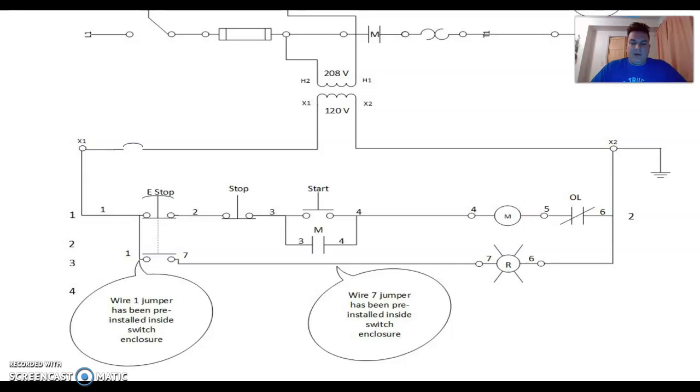Something that's really popular is using either an e-stop or some type of proximity sensor to a control relay, what would be known as a master control relay. Essentially, the e-stop will turn the control relay on and off. And the control relay will actually be used to switch the X1 and X2 rails with 2 normally open contacts, or you could do normally closed, or there are different ways of doing it.